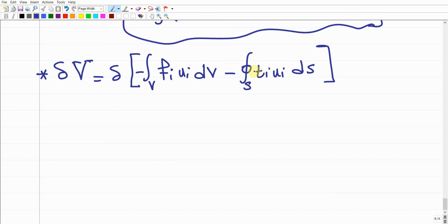But in the conventional use of linear elasticity, these body forces and surface tractions are independent of the displacement fields. So that's why they don't have first variations. This indicates that the integral, the body force, the surface traction, and the surface, all of these four quantities, are independent of the displacement and don't have first variations, so we can deal with them like constants.